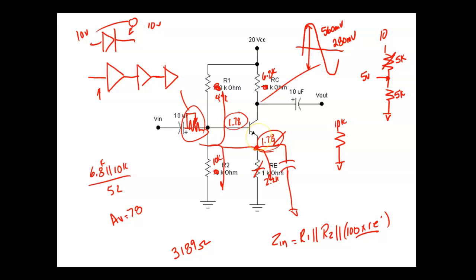Okay, so what are we going to do next? Of course, I dropped my lab book on the thing. So the bias on the base went up. We were expecting 1.7 volts. It went up to 1.8 because now we don't have that resistor out there. Okay, I'm listening. What's next? Yeah, I'm sorry. Let's measure the collector voltage.